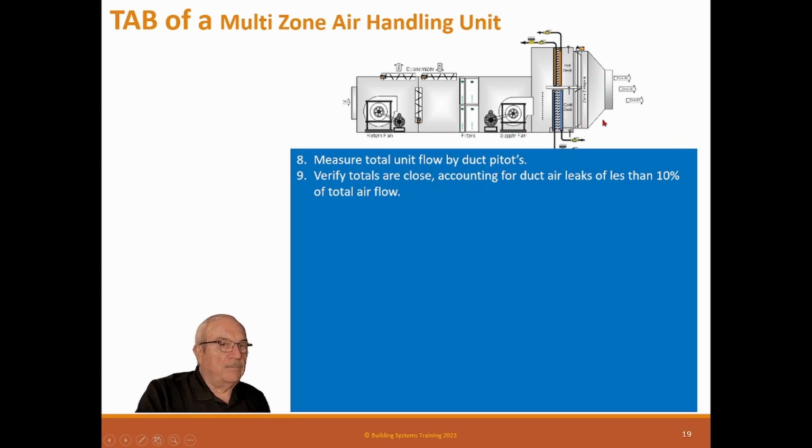One area of problematic duct leaks is that joint between the zones. Right here at those dampers, when you have one zone that includes 4 dampers, one includes 2 dampers, the joint between them is normally only 1 inch wide. It's the flange of your duct. And if there's a leak there, it's really difficult to seal. So those are problematic. And if you have a lot of duct leakage in multi-zone, I would check there first.